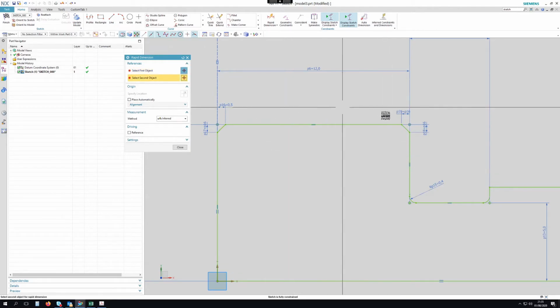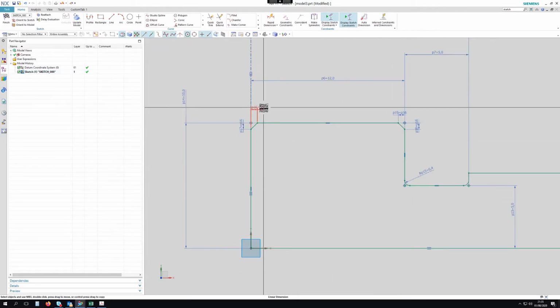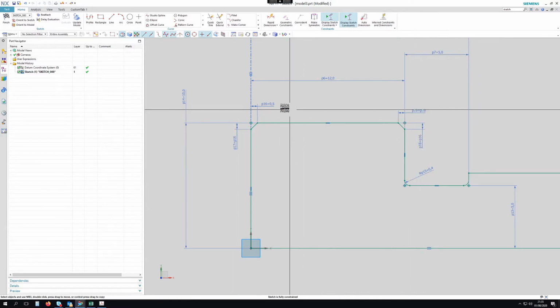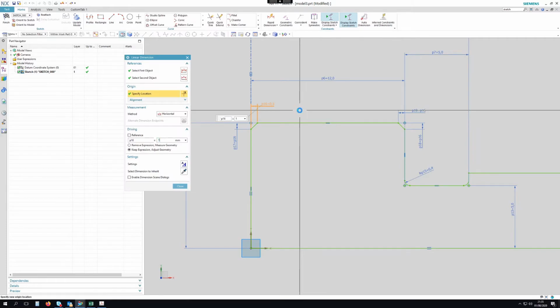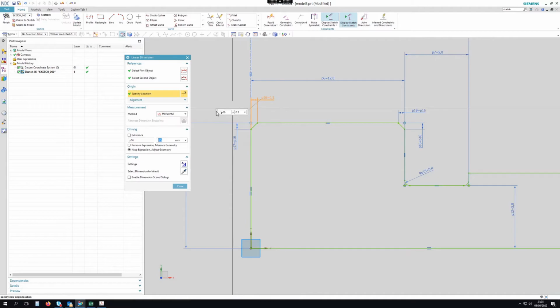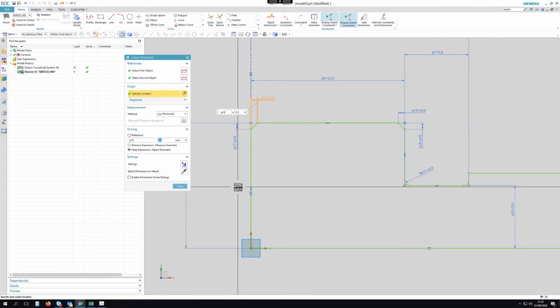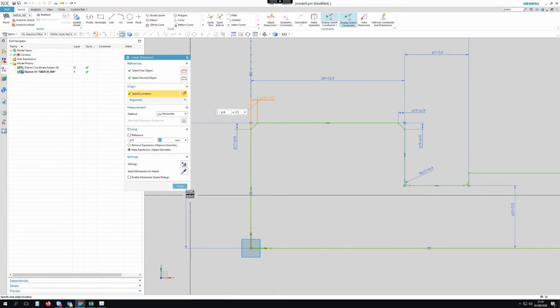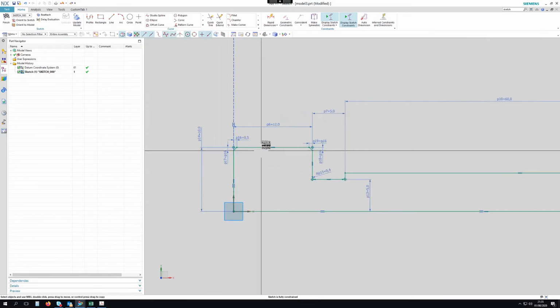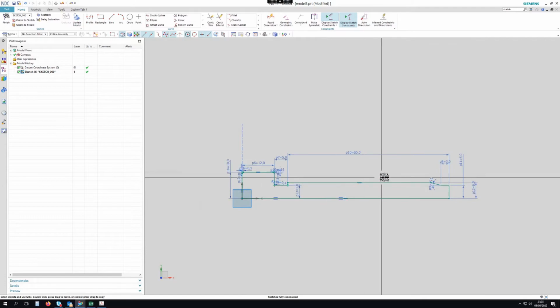Right, so here if I want to change the size of the chamfer, I just need to change this one dimension and everything else will change around it. So I want to make that 1.5, so it makes life a lot easier later on, because when you're designing something it's never right first time, every time. You always need to tweak it a little bit here and a little bit there, and things like this make life easy.